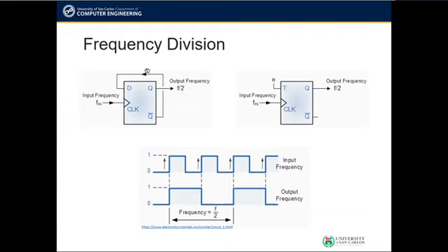What happens on the D flip-flop is that at every active edge detected at the clock input, in this example the rising edge, as shown by this upward facing arrow, the Q bar or inverted output of the flip-flop is taken as input back to the D flip-flop input and shall be shown at the output.